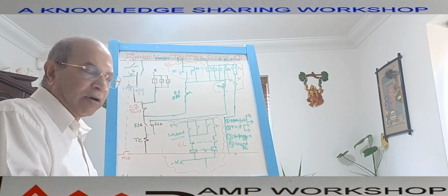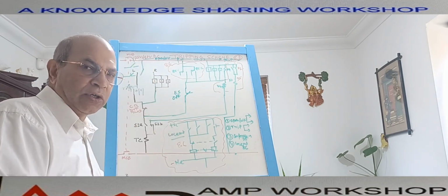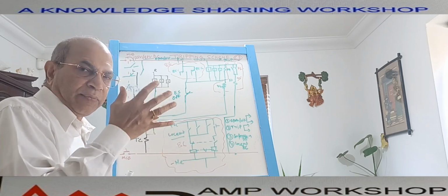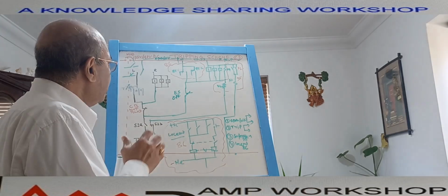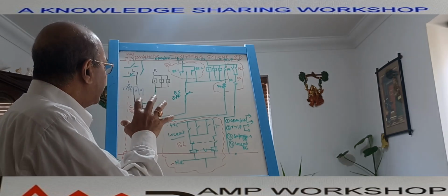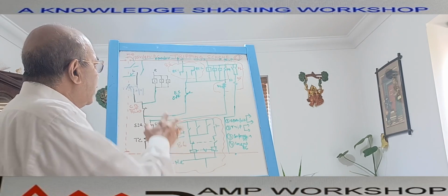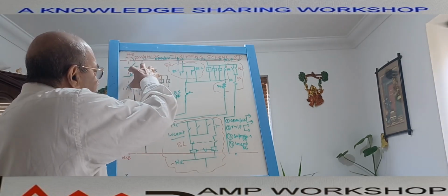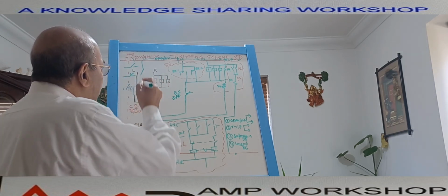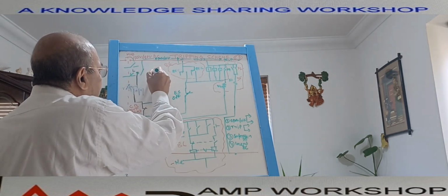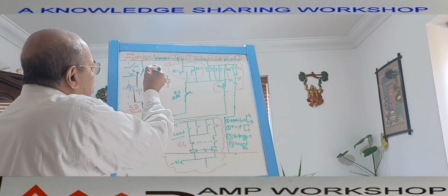Here we are considering the switchgear panel where the circuit breaker is physically located. The same panel is the local position. This local remote selector switch, which has multiple auxiliary contacts, is located on the switchgear panel, and we have selected the switch in the local position. There are two positions: one is a local position, another is a remote position. This is a selector switch, and we can move the switch to either this position or this position.